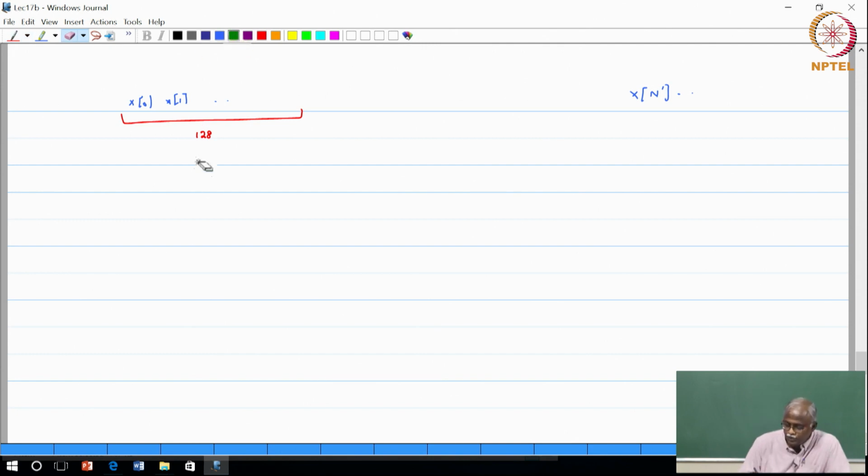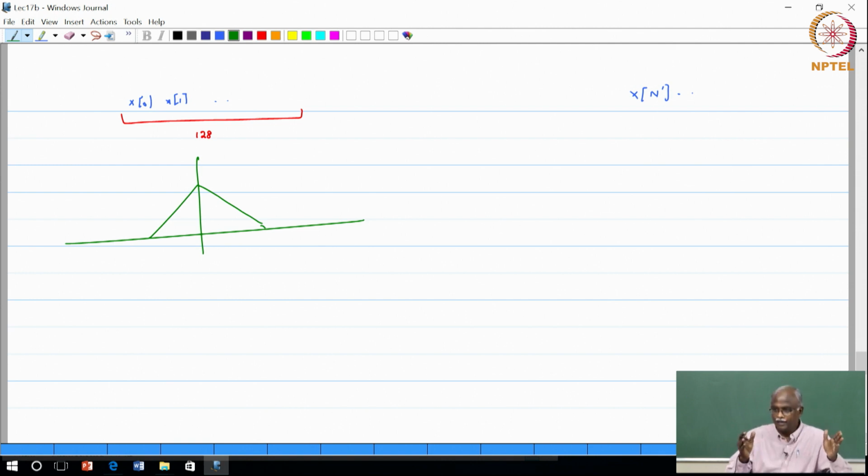So, if my input spectrum, the true spectrum, had this shape, the minute I multiply it with a rectangular window, I have modified my sequence. It is no longer this spectrum. So, actually what is the spectrum? It is this convolved with a rectangular window. Spectrum of a rectangular window is a sinc function. Okay. So, already I have modified it. So, you have to go back and revisit what I am calling the delta function, because it is actually about how we interpret the process.